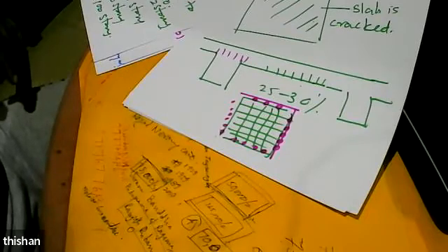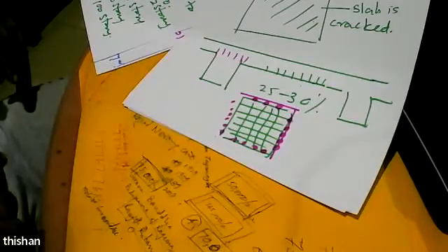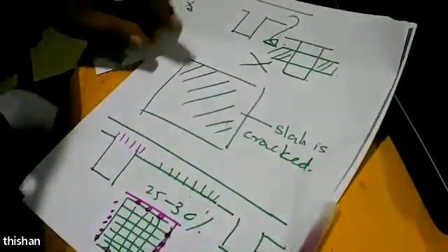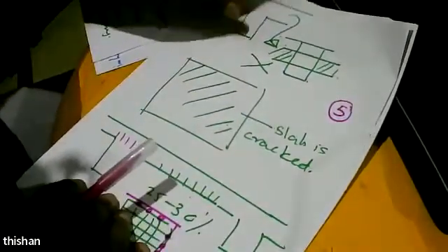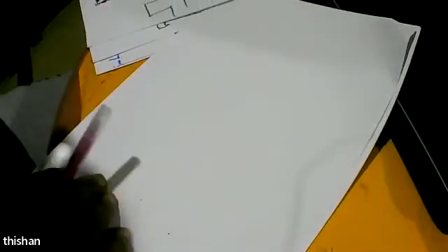Now you can see it is far better not to model these slabs, provided that you can get the correct load transfer by using some method. It can be a manual method, some programs give automatic methods. For example, programs like ETABS, you can have this happening automatically while the program is running, and MIDAS also, there are so many facilities.